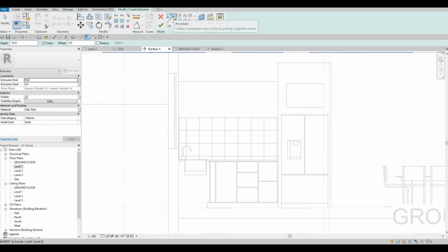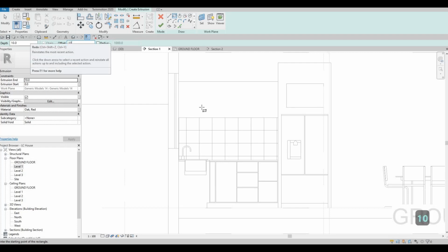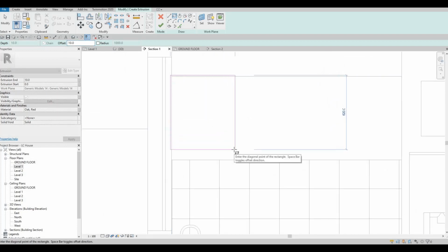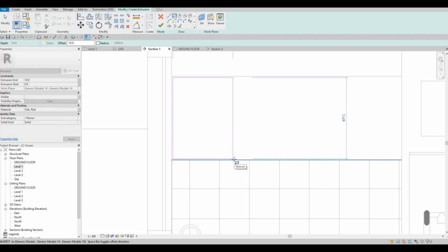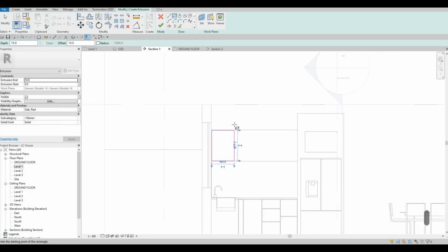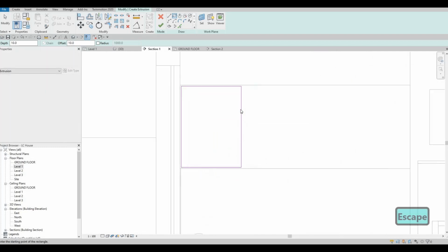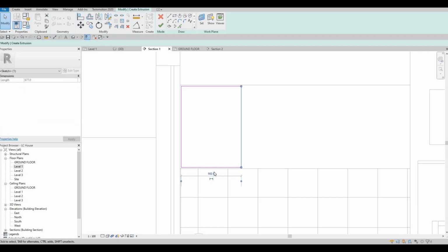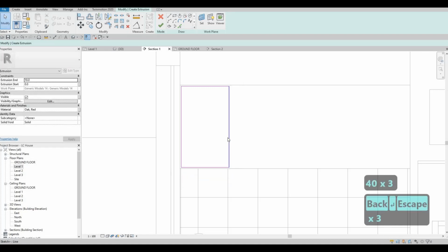And then once we set it on the top, we need to click on rectangle, and the extrusion will be 10 millimeters, sorry. And then the offset should be 10 as well, so that we have some gap. And then we need to put it in the midpoint right there, and then offset from the inner line. I want to see how much we have, so around 400 probably. I'm gonna retain that space, and then tab,